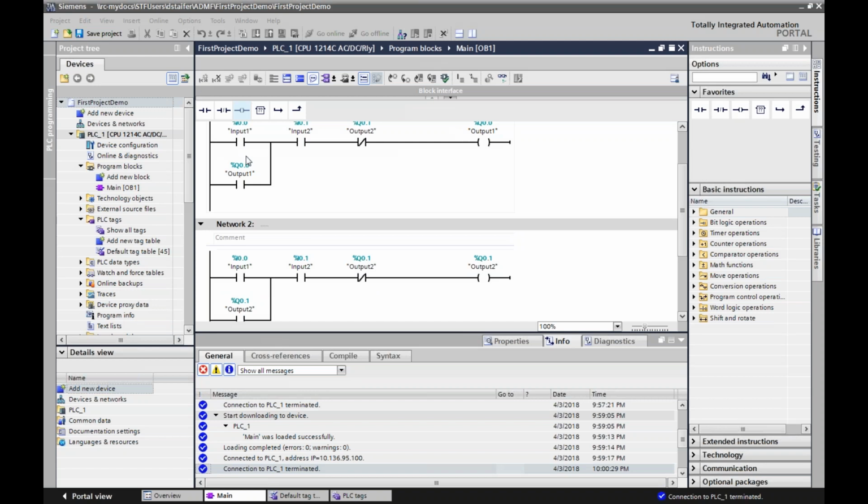And so what this is saying is input 1 is pressed and input 2 is high, and input 2 is not running, turn on output 1. And let me make this output 1, sorry. So input 1, input 2, output, when not input 2, output 1 turns on. And then down here, when input 1 and input 2, it turns on. Now, let's see if this fixes it.